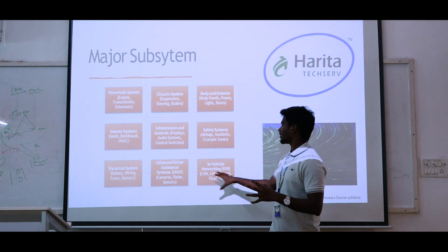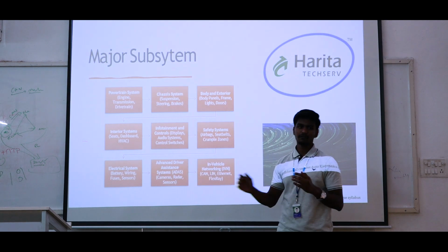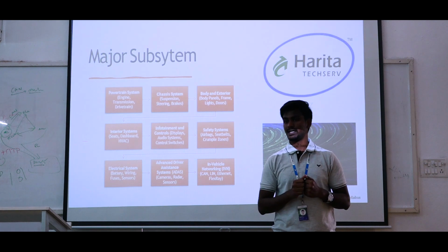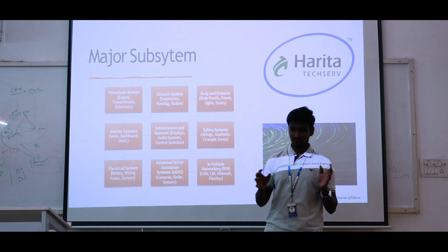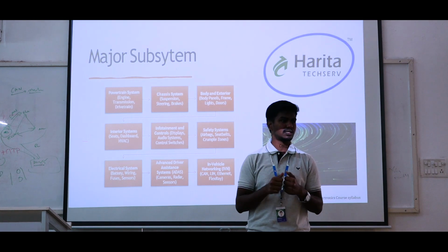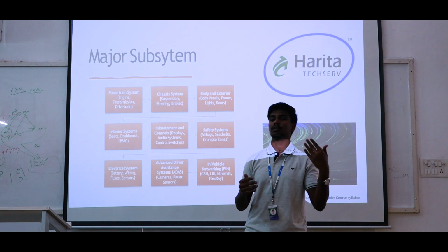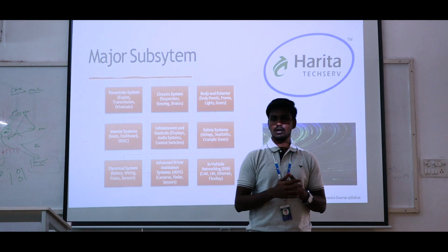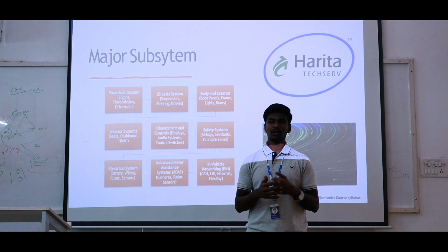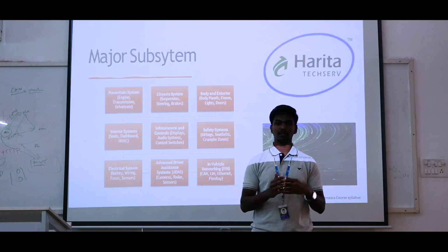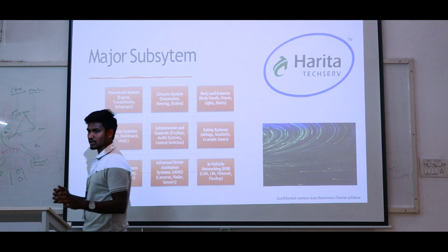These all communicate with the individual ECUs, but between the CAN, LIN, or FlexRay ranges, there are gateways. The gateway receives the CAN values, LIN values, FlexRay values, and Ethernet. These all communicate with one box called the gateway. This gateway splits the values to decide which one to allocate them to. We are going to write the program for that, which is called signal splitting. For this, the base is the C language. If you don't have knowledge of C, you can easily write the communication access with C programming. It will be easy. So these are things we will cover in our program session.